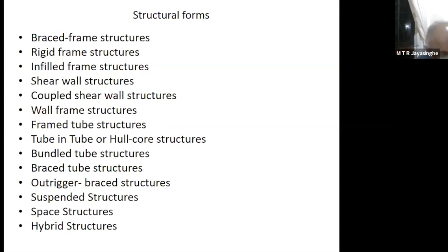Slab design diaphragms for lateral load shouldn't consider this factor in reducing slab thickness. Not a problem. The moment you have anything more than 75 millimeters, the diaphragm action will be there. Don't worry. Anything more than 75 millimeters, you cannot deform the slab in its own plane. So diaphragm action will be there. Don't worry. You can reduce the slab thickness as much as possible.